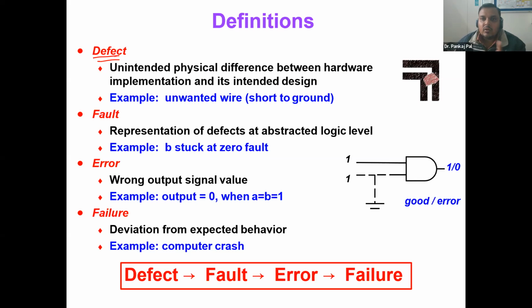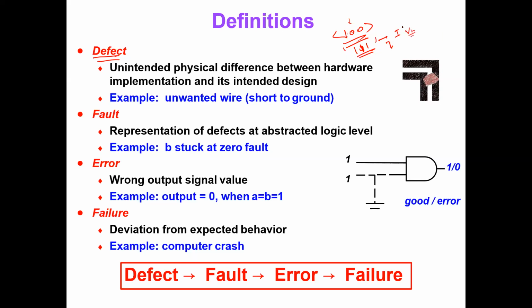Like if you take the example of orientation, I think most of you know that for making any surface device or MOS device, we generally prefer the 100 orientation. But if you get the 111 orientation, what does it harm? It will reduce my overall current. Specifically, the surface effects will be more in the 111 orientation, so that will give me a lower threshold voltage. So these are the defects, but we cannot handle all of them.